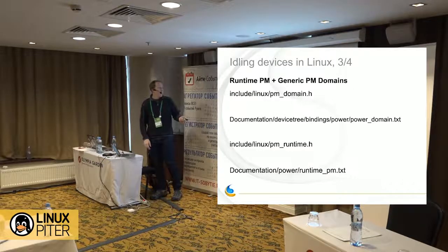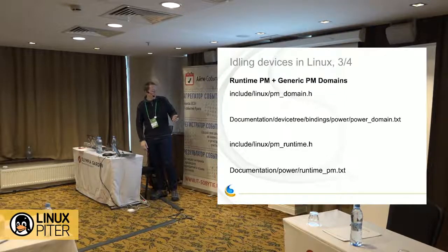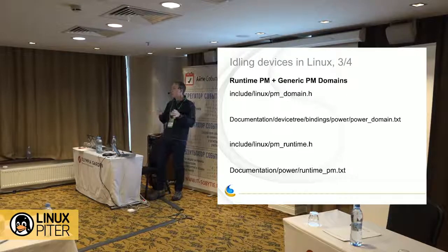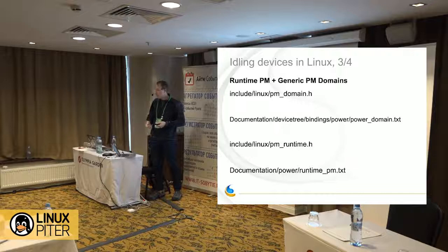These are the relevant headers and documentation. If you're not familiar with these before, pmdomain.h, pmruntime.h, and there's some good documentation out there as well. There's a nice device tree binding for defining power domains, which is very important because I mentioned before that you have to attach a power domain to all the different devices that use it. And in the ARM world, device tree is the way we create linkage between devices.